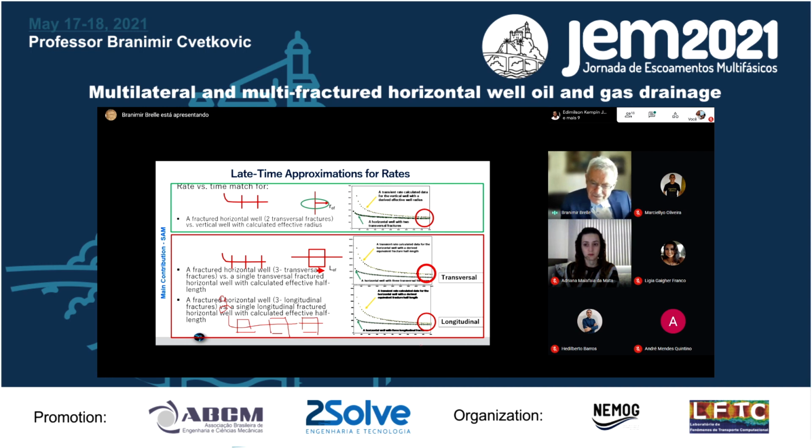Here, the solutions are much closer. Why? Because I don't have a pressure drop here, you see? In this case, I have this fracture, but it has this connectivity. This fracture has this connectivity, and the third fracture has the connectivity like that. I have a huge pressure delta P. That is why you can see the difference is huge. It's maybe 5 times bigger than this one here. See? So a transversal fracture has a problem of choking.